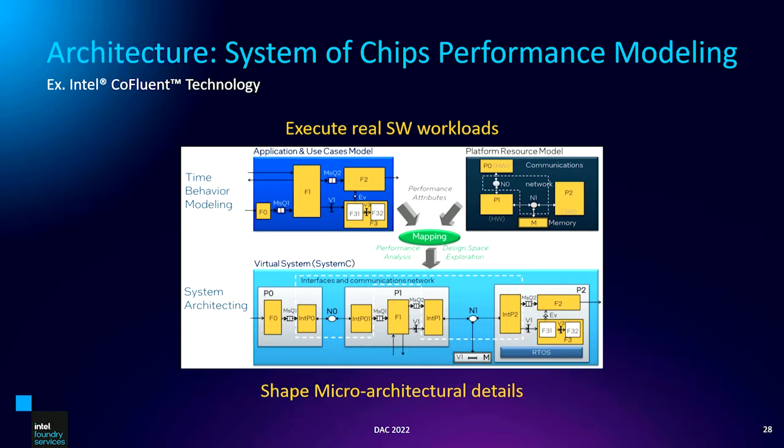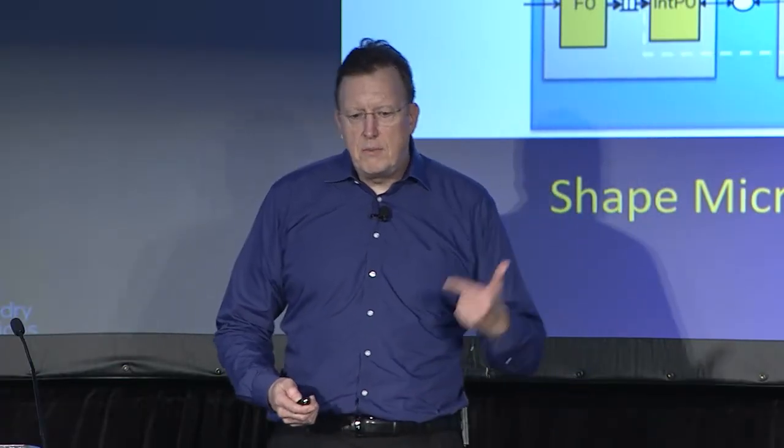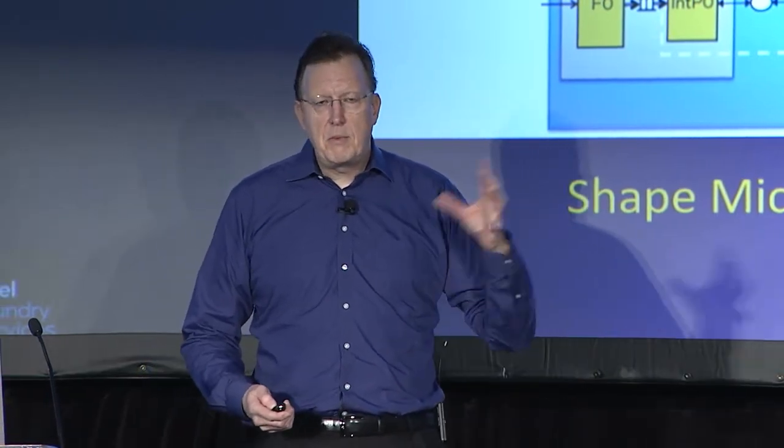For example, if I take X number of units and I break them up into different coherency domains, obviously you're going to pay a penalty in terms of packaging technology, you're going to pay in terms of latency and power and so forth. And the architect has to know that their workload at the end of the day is going to work as intended, right? So the performance modeling tools exist, they just have to be modified to work with chiplets.